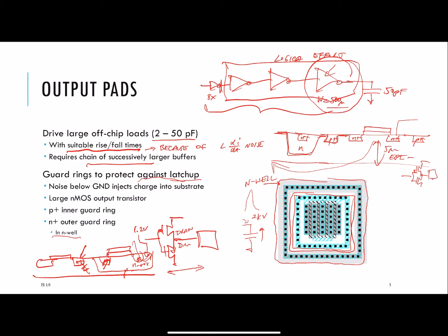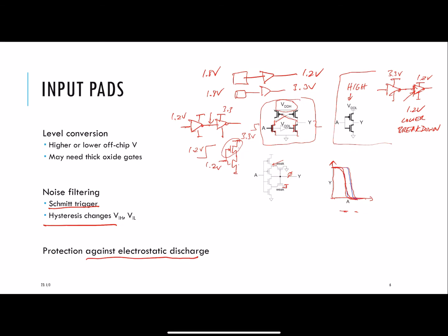You still need to take some other protections, but anyway, they're less susceptible to issues. In the inputs, though, the input pad, like I'm drawing here, unless you do something, all you see is a gate capacitance. You just see a capacitive load.